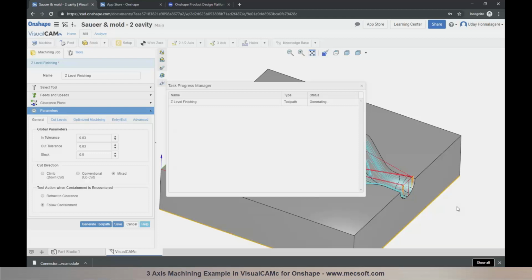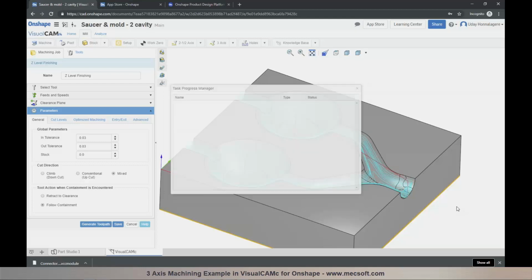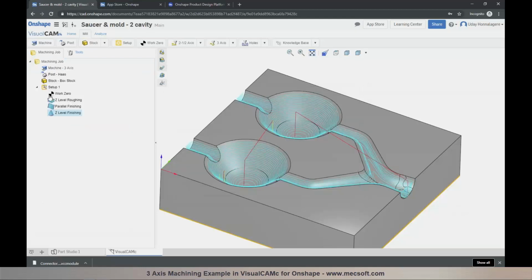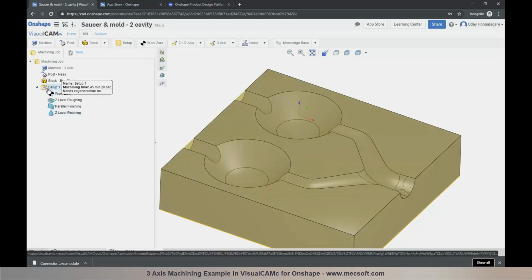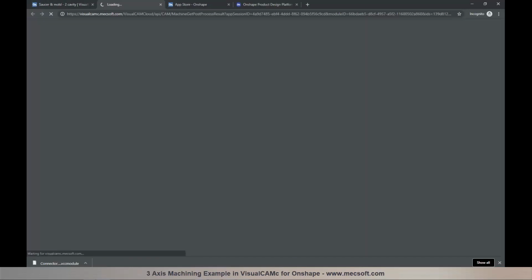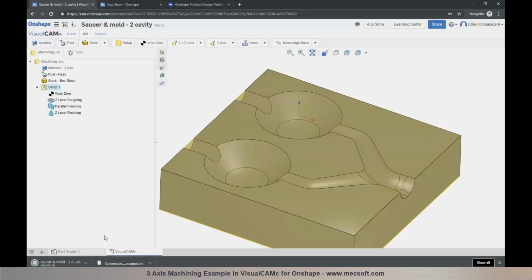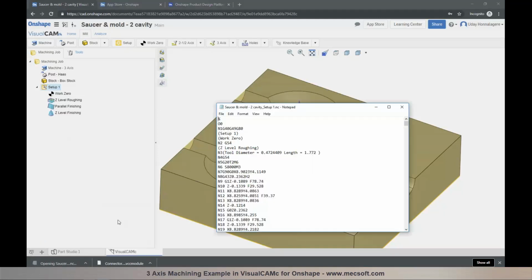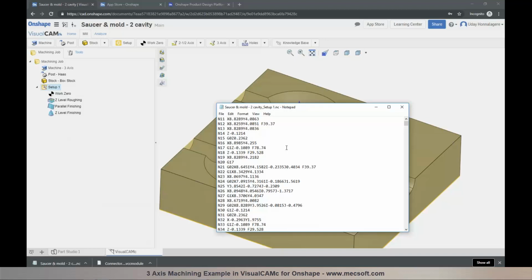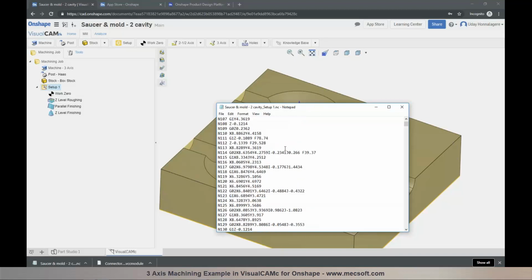So once you have all of your machining operations programmed and generated, you're ready to post-process, very similar to how we did on the 2-axis and 2D part. So I'm going to hit save, select the setup. To estimate the time, it's about 45 minutes to cut this part. Right click and post-process is automatically going to download the posted output file onto your desktop computer. If you're running Windows or a Mac, it'll just download it and automatically use the document name and the part name for the file. And there's your posted output file ready to be sent out to your machine tool.